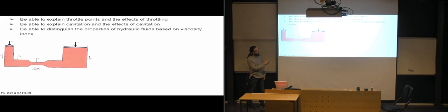The main problem with the cavitation is that it's going to release the energy, and if the energy is released in the middle of the fluid, it's mostly just going to create heat in the fluid, so it's not that big of a problem. But usually you're going to get a lot of turbulent flow here, so it's going to be pushed towards the walls of the valve or the pipe or whatever it is, and be releasing the energy in close proximity to the wall, and that's going to damage the material there.